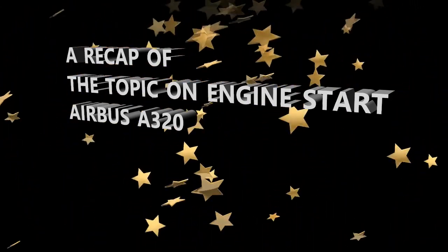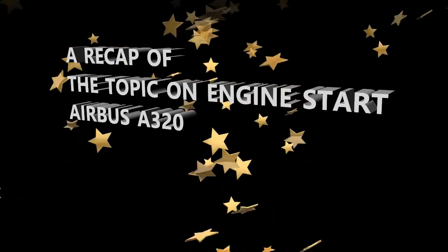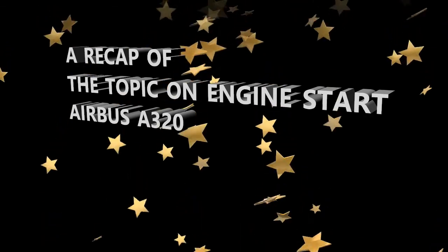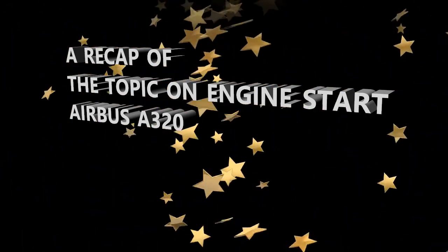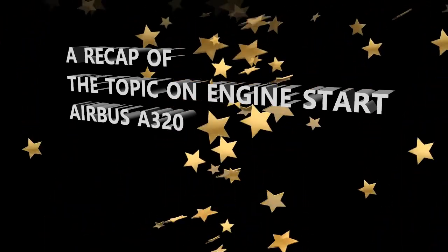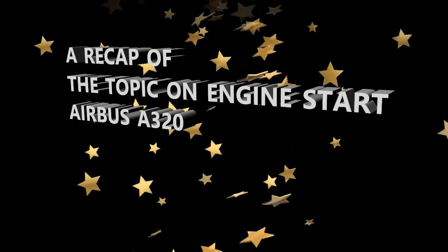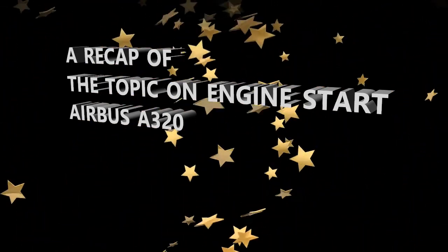Automatic start, manual start, your continuous relight, and then mentioning the controls and indications that you can find on the eCAM, and also knowing that there's a single chime, master caution lights come on, as well as the engine fault lights that come on when there is a fault. So that gives you a rundown for the most part of the engine starting.